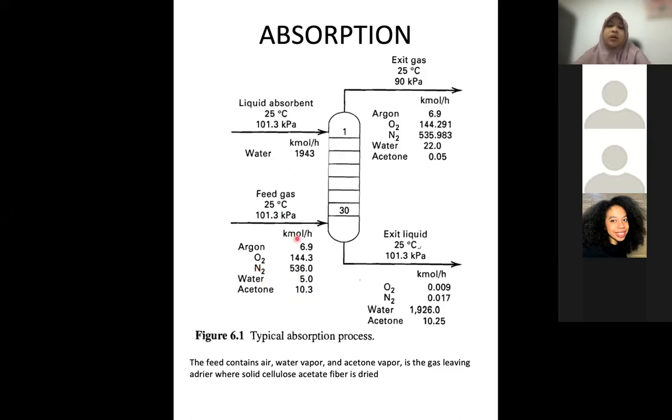Okay, and then we also have to select which liquid absorbent can absorb the component that we want to remove from the gas stream. In this case, water is actually good to remove acetone because both of them are polar solvents. So the water can take that one there.